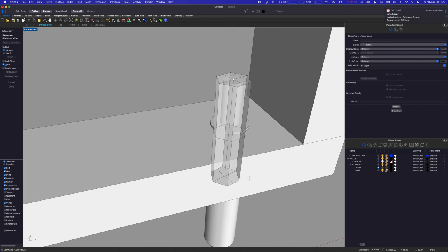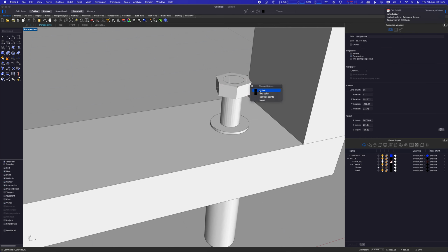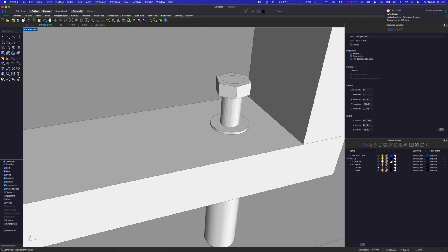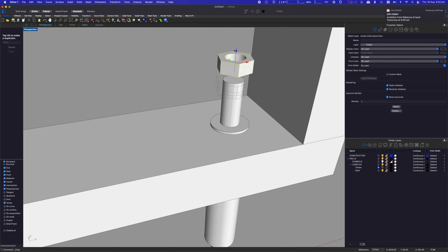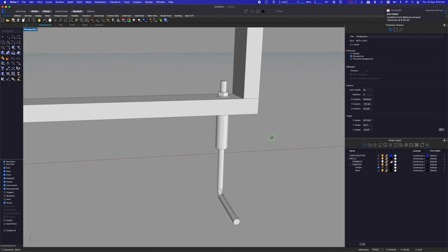Let's make it say what looks right, maybe 10 millimeters. Whoops, that's 110. Let's delete the curve. Let's Boolean difference the rod, and now we have a nut. So we'll move that vertical from there to there. And there we have our little assembly.